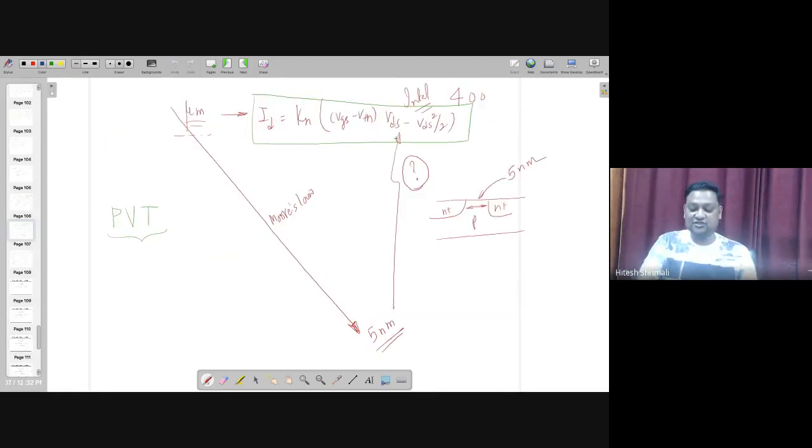and those 3 equations can be checked with the original device made in 5 nanometer. In the company, the compact model engineer or the process engineer fabricates the device in 5 nanometer. They look at the IV characteristic and check all the parameters against what they derived mathematically, and some fitting parameters need to be added.